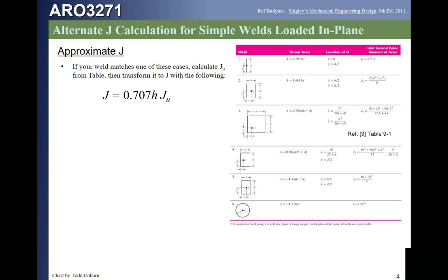Another word of caution is in order, because these welds are given dimensions like B and D. Often, the problem statement will also identify dimensions, and sometimes it will use symbols like A, B, D, and H. Just because the figure on a problem statement or in somebody's sketch uses one nomenclature does not mean that same nomenclature applies to this particular table.